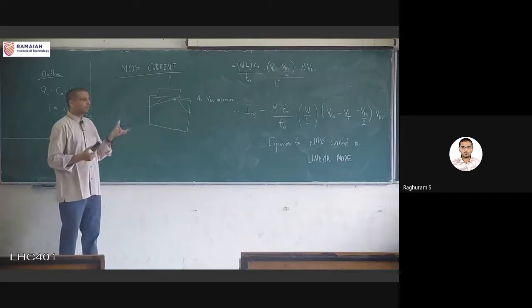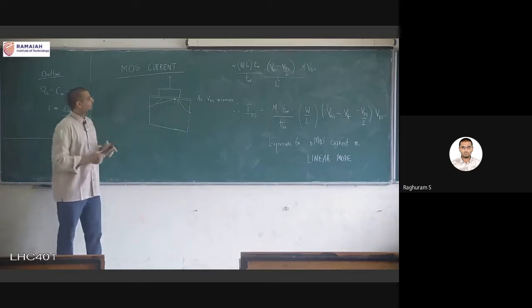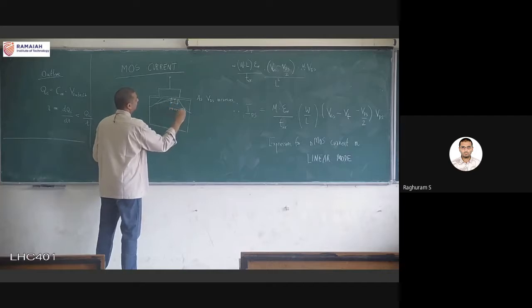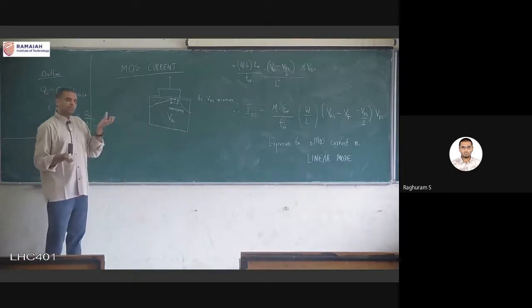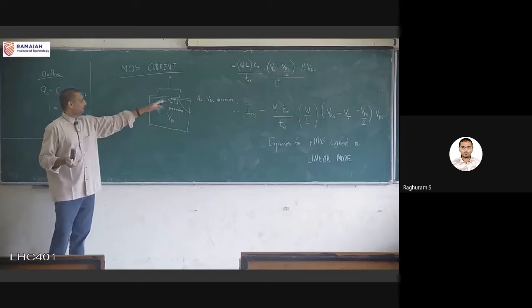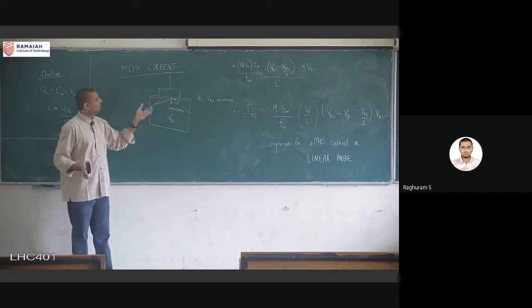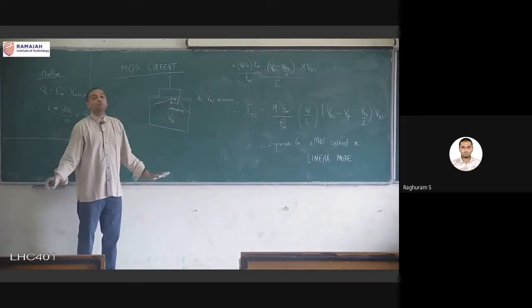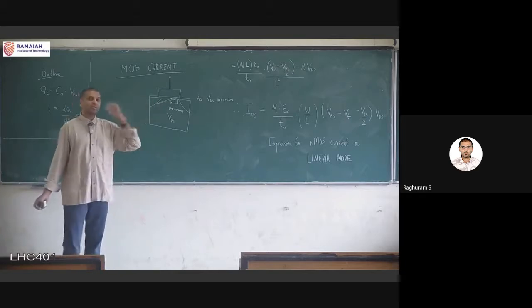Some amount of VDS is responsible for moving the electrons, but beyond a certain point, with increasing VDS, the pinch-off point starts slowly moving towards the source terminal. This is highly exaggerated, not by this much. But as we keep increasing the VDS, the excess VDS appears only in the pinch-off region where there are no charge carriers. So the excess VDS is not responsible for the horizontal movement of the electrons.